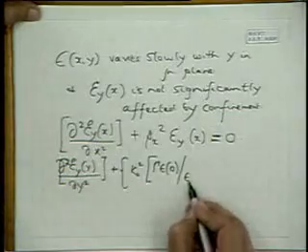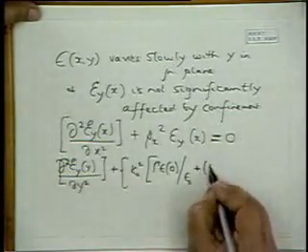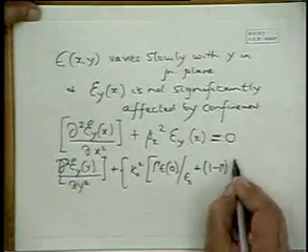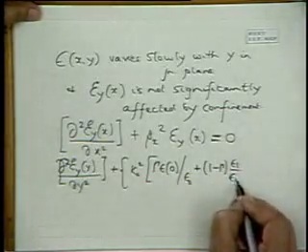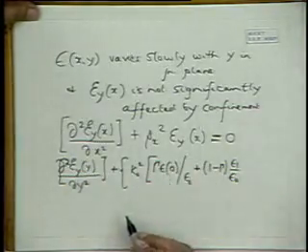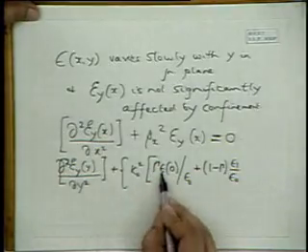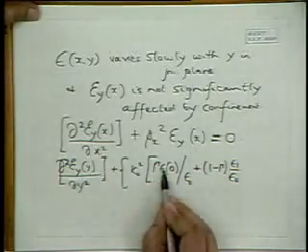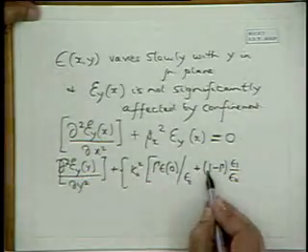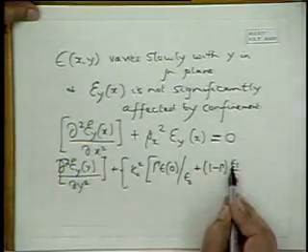This is at x equal to 0, and epsilon 0 is a free space, plus 1 minus gamma epsilon 1 by epsilon 0. This is significant. This type of variation we will come across later. Within the active region, we have epsilon gamma, and outside the active region, there's 1 minus gamma into E1.